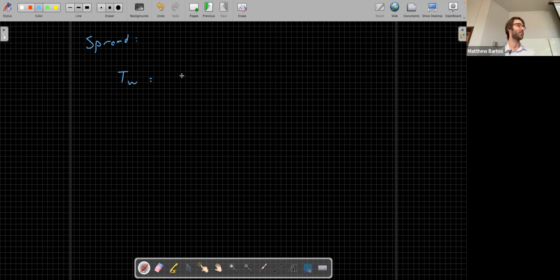TW is equal to 5.6. You can get this simply by rearranging Izzard's equation, so that we have Qn in the numerator, and K times the lateral slope to the 5/3 power times the longitudinal slope to the 1/2 power in the denominator, all to the 3/8. If you compute this, you should get about 5.6 feet.